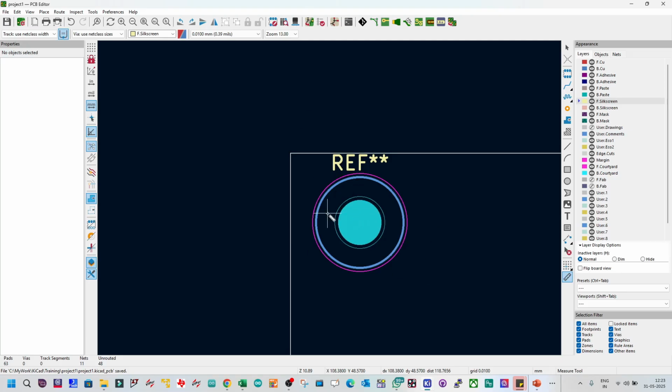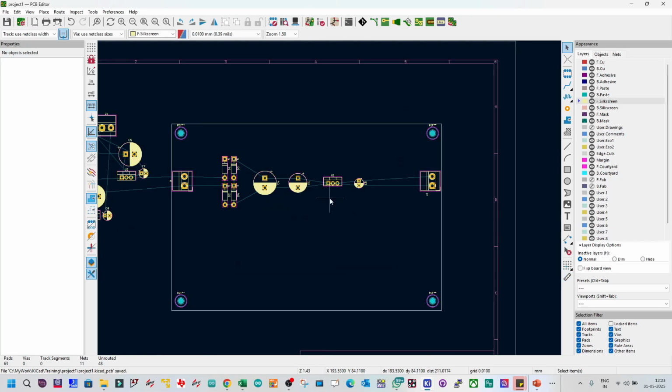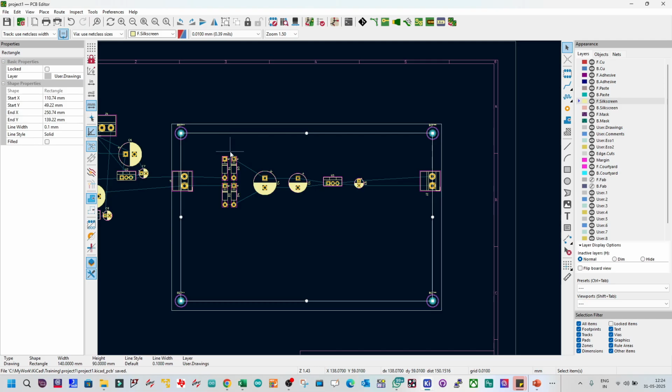So to do that, there are multiple ways. What I have done, I have drawn a rectangle 5 mm away from the boundary, 5 mm, 5 mm. So this dimension is 150 horizontal length, vertical is 100, 150 by 100. So 5 mm from all the directions. If you do that, 10 mm will be the reduction. So 90 vertical height of this rectangle is going to be there, and 140 is going to be the horizontal length. So that I have done the alignment. There are multiple ways to do that. You can do a practice. Just draw it. Do you see this mechanical?